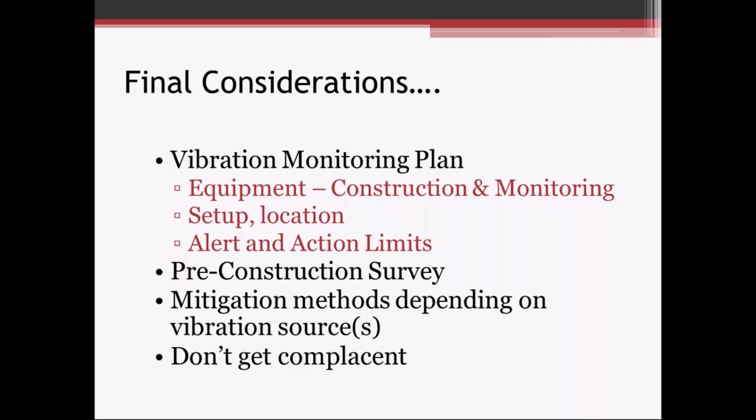Maybe you're pre-drilling some of the holes for your piles, to maybe intercept that Rayleigh wave, that surface wave. Maybe you're digging a 4-foot trench or something around a critical structure that you don't want a lot of vibration getting to. Digging that trench, again, the idea is to intercept those surface waves, those Rayleigh waves, a little bit.